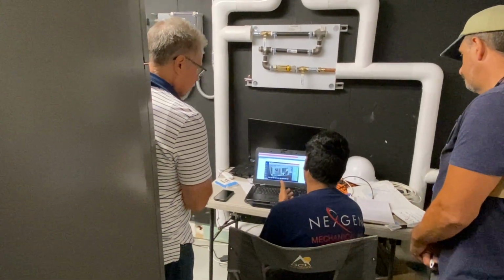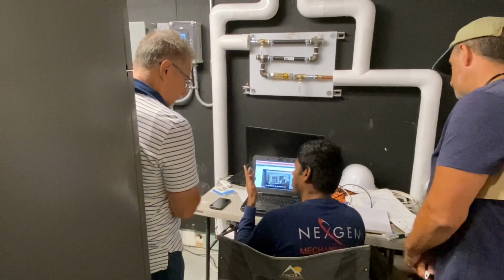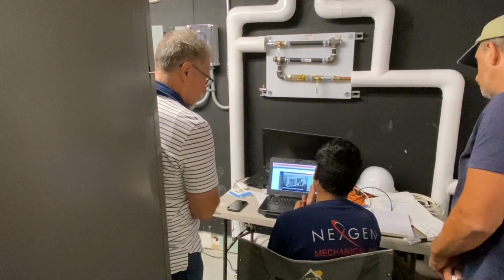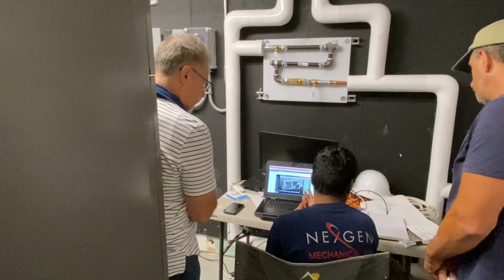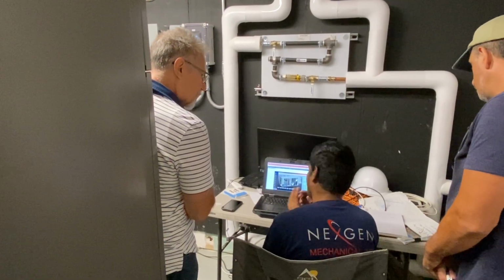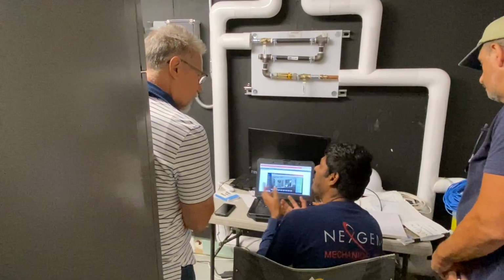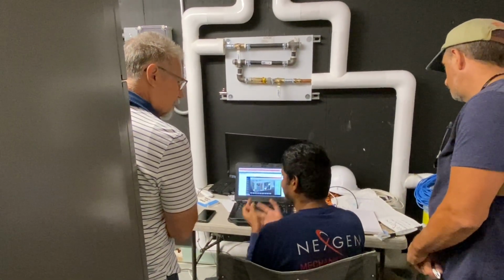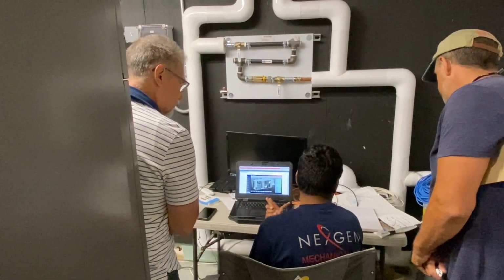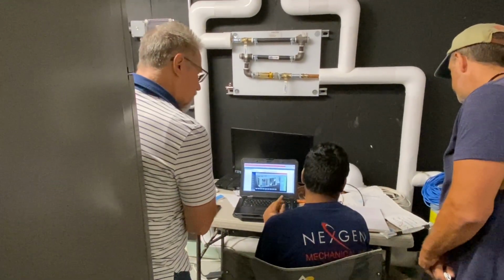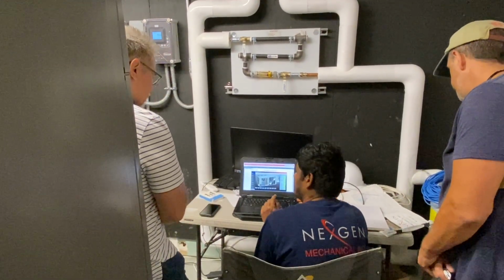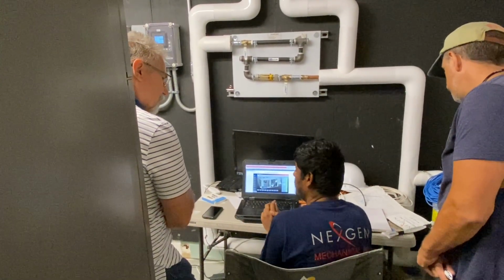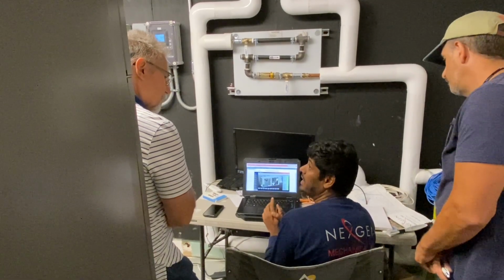We talked about the economizer operation and the CO2 control, we talked about the wheel operation, and we talked about the discharge air cooling. I think that's what we have. Other than that, the three important things here are the warm up mode, the cool down mode, and the dynamic set point change that happens. I think that's it. It's going to recirculate 100% either when it is in a cool down mode or a warm up mode.